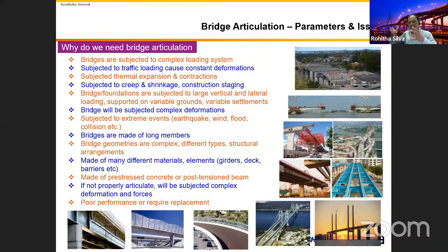Yeah, you can see if you design a bridge with the elastomeric bearing, a low bridge, like I explained to you, the expansion joint distance could be as long as 300 meters. So if your bridge is sitting on the elastomeric bearing, in the earthquake situation, the earthquake generates from the ground, the substructure is moving. Because it's sitting on the elastomeric bearing, the superstructure movement will be significantly less because of the damping effect of this bearing.